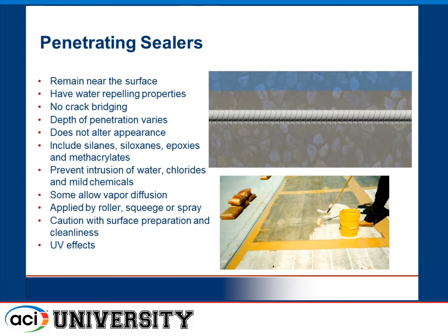Maybe some of the coating will penetrate into those cracks and will provide some capability to keep the water or the moisture out. The depth of penetration varies depending on the manufacturer and the type of material that is being used. It doesn't necessarily alter the appearance, except that it may change the color a little bit, as can be seen in that lower photograph right here.